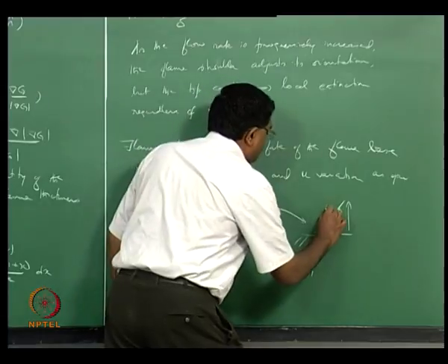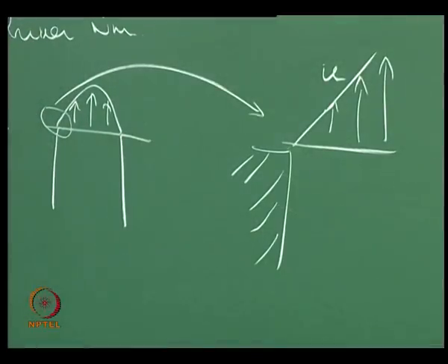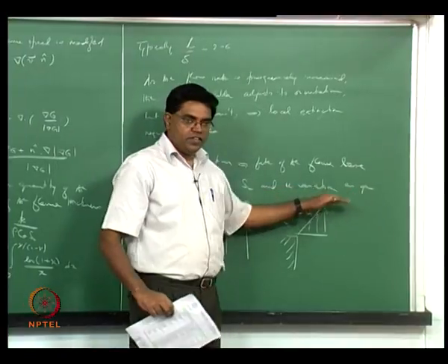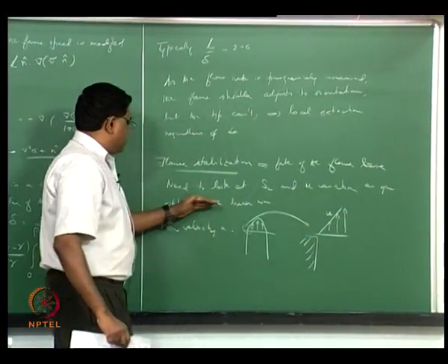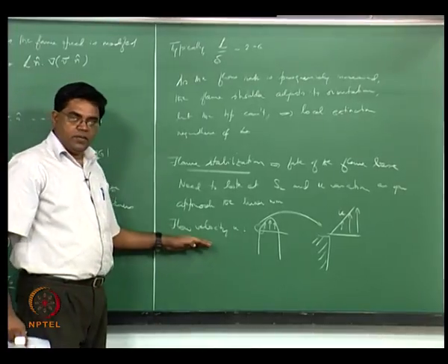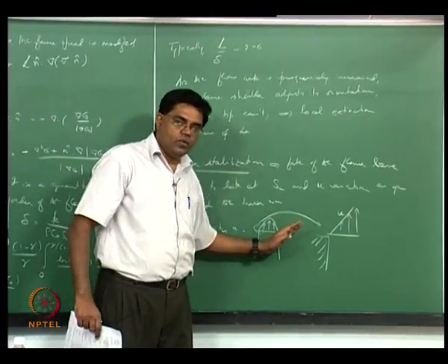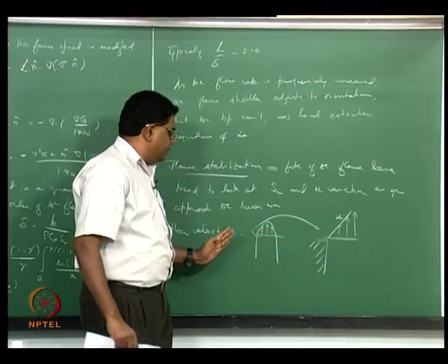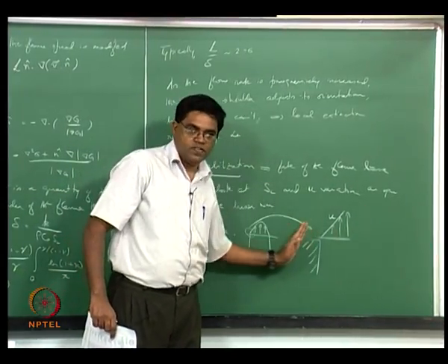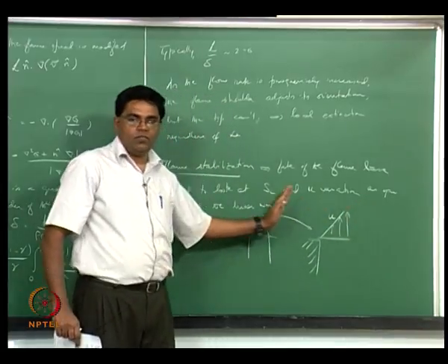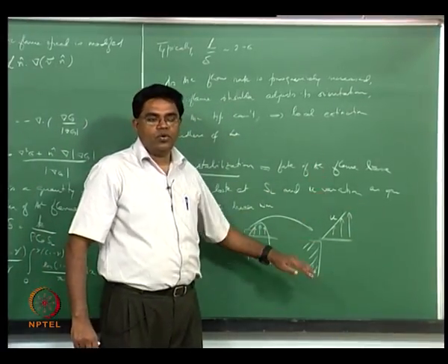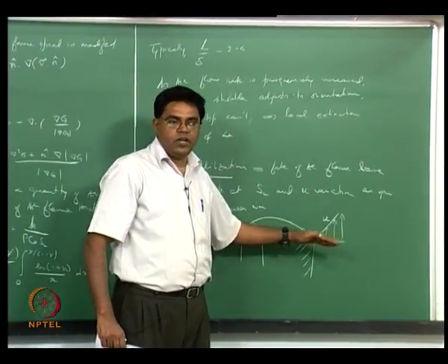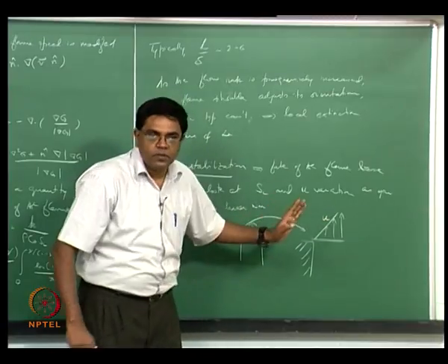That is your U. So when we said that we wanted to look at the flame speed and the flow velocity variation as you approach the burner rim, we picked the flow velocity because it is always going to be somewhat linearly increasing from the rim inwards towards the center of the tube. So that is more like a monotonic variation. You increase the flow speed, the slope is going to increase. If you decrease the flow speed, the slope is going to decrease, that is all.